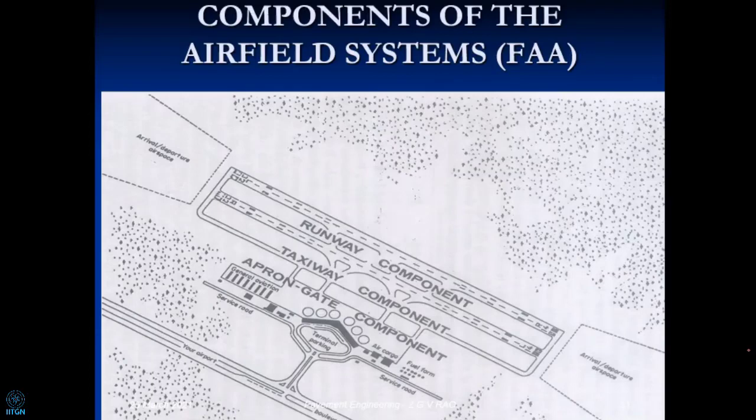So that is why you always feel that in monsoon conditions, we have to keep our fingers crossed when the aircraft land during severe weather conditions in Bombay, because that's how the airport is made. Maybe the new Bombay runway is going to be different. The other thing is that drainage is important along and across the runway and also in the neighborhood. So drainage is important in the entire airport area.